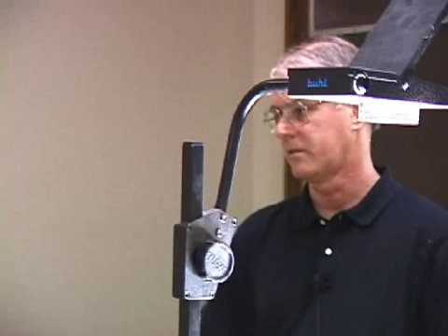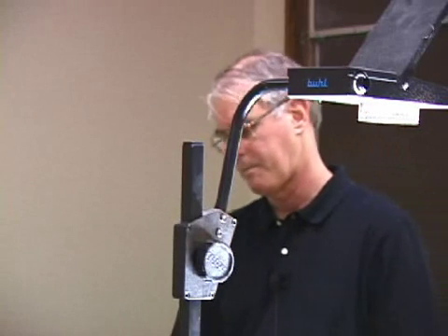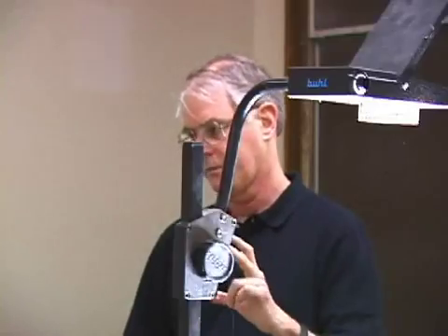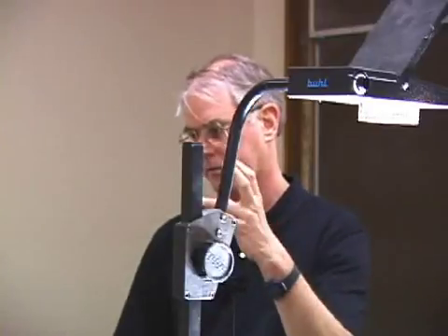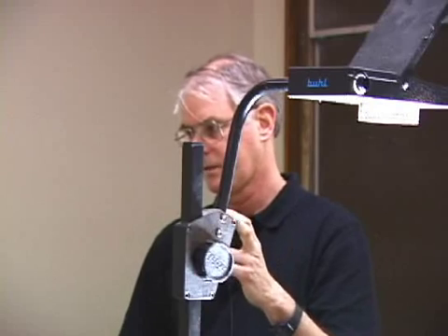Okay, I'll jump to what I think is going to be a problem later on, and that is that you have to cancel 140 dB of noise. So the rule of thumb is you get 6 dB for every bit of A to D conversion you get. So you're going to need of order of 30 or so bit A to D converter to make sure you've got enough. That's probably not a problem.